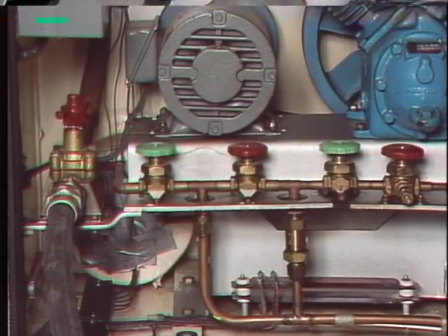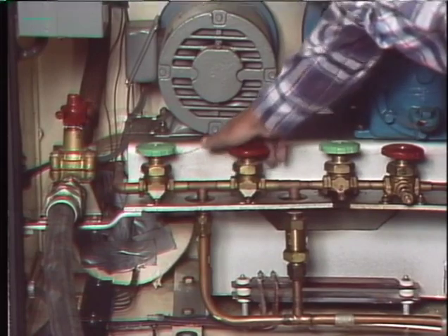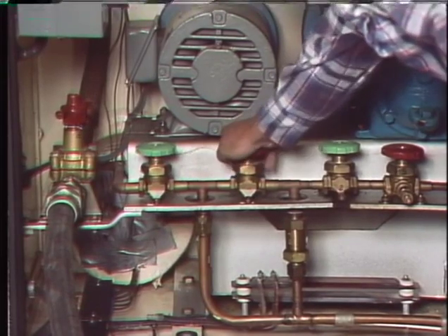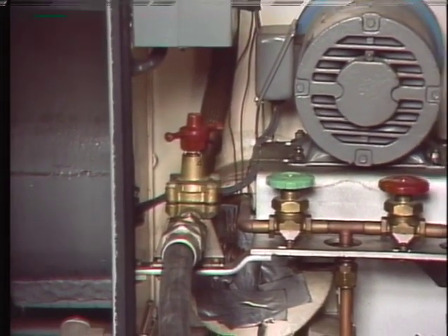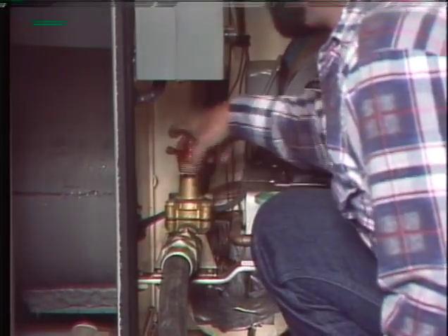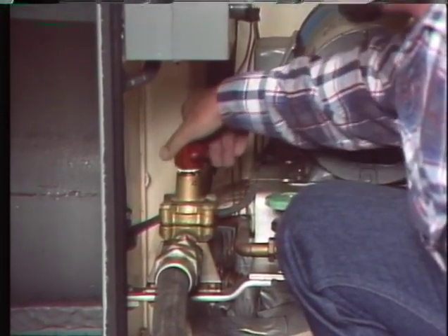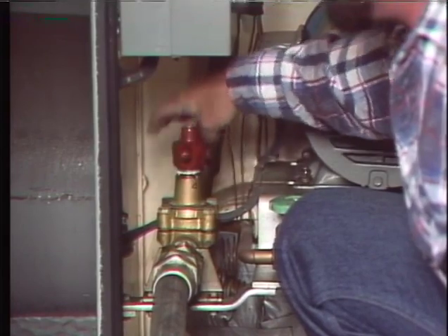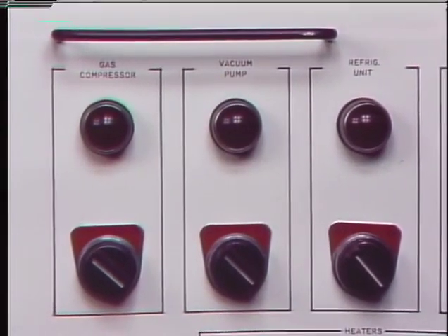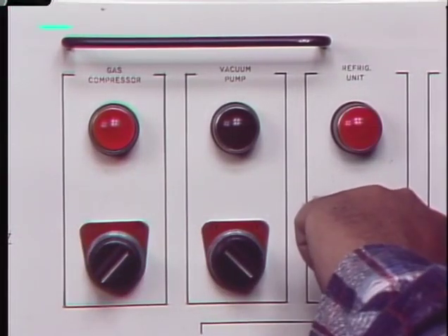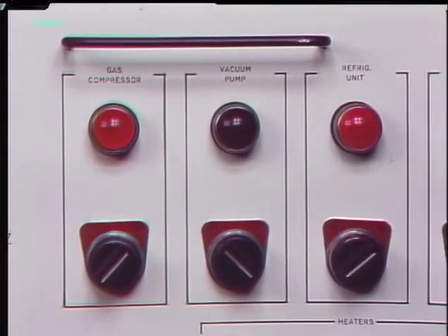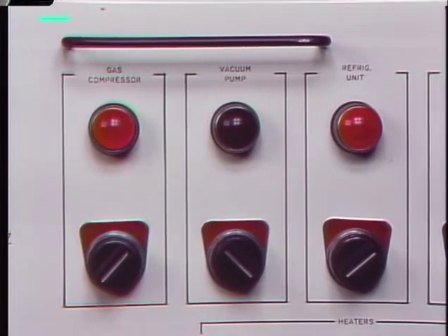Next, a valve is opened at the breaker to allow gas in the high pressure system to flow to the low pressure system and equalize the pressures. When the pressures have equalized in the breaker, a main tank cutoff valve is opened to allow the gas to flow from the breaker to the storage tank until pressure between the breaker and the tank equalizes. Then a compressor is started at the trailer to pump the gas out of the breaker. A refrigeration unit is also turned on to keep the gas from heating and expanding as it's transferred into the storage tank. The compressor is allowed to run until all the gas has been evacuated from the breaker.